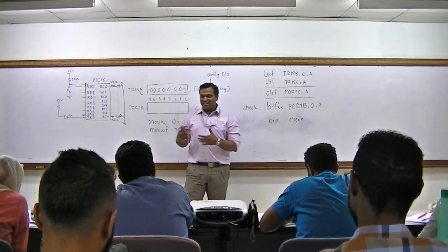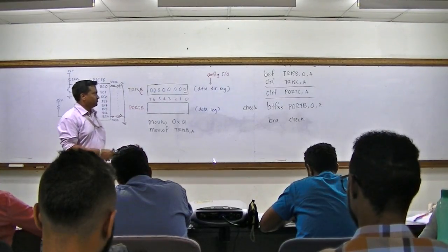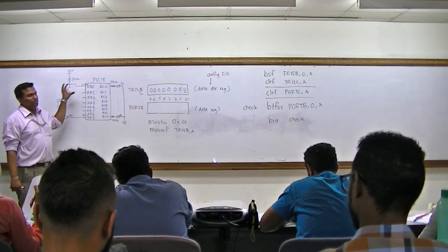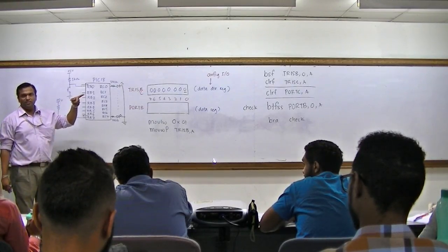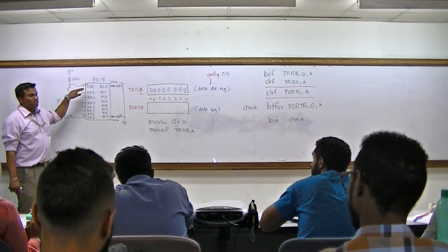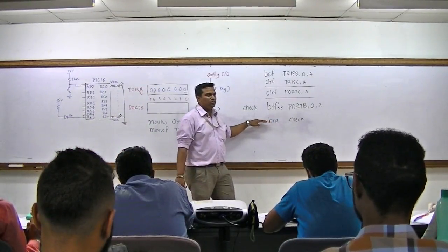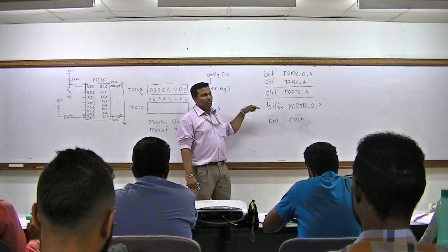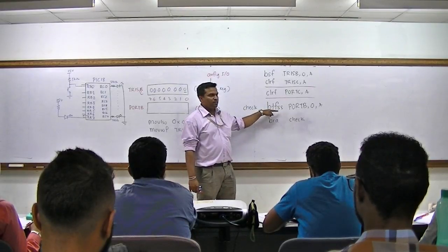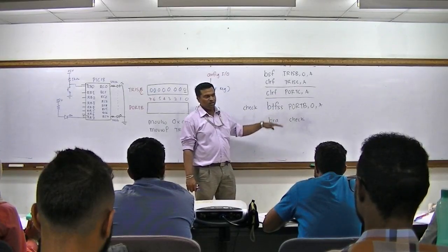So now just to recap, set is 1. Clear means logic 0. Is it okay? Why are we using this configuration? Because this configuration gives us two logic levels, 1 or 0. So when you're not pressing the switch, the logic is 1, which means the button is not pressed. So it will skip, it will come here. So we need to constantly keep checking. Now if the button is pressed, what happens to the logic? It becomes 0. So will it skip? No.